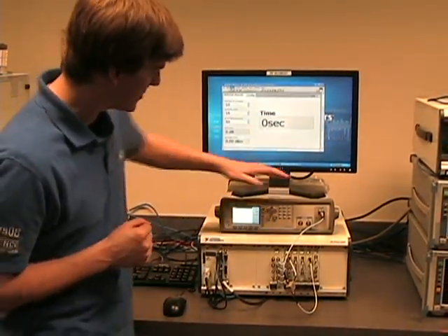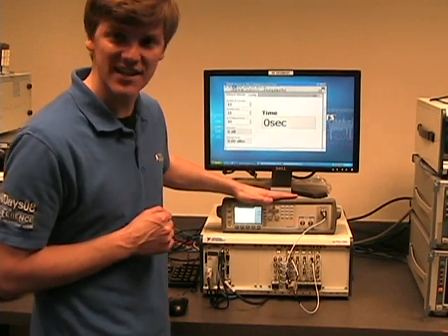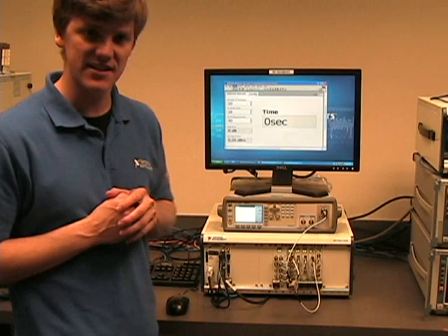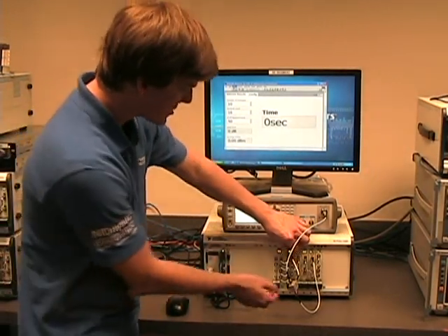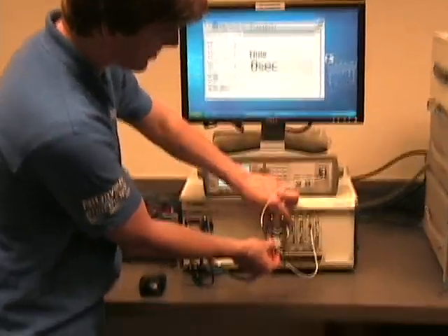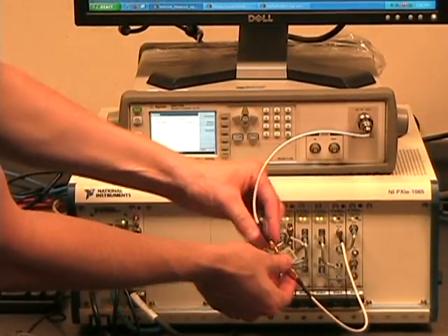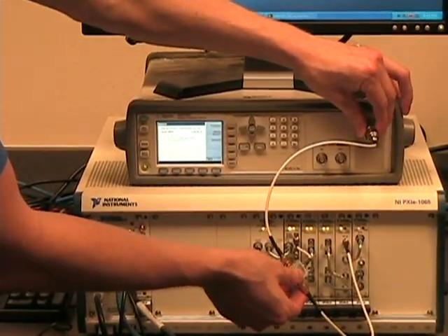And one of the things that we're going to find is that the high performance of dual-core controllers allows us to achieve significantly faster measurement times than with traditional instruments. Now the traditional instrument we're using today is the Agilent N4010A, which is one of the most common wireless LAN test systems on the market. So what we're doing is we actually are using our PXI vector signal generator, and we're splitting our signal out to a PXI vector signal analyzer, and then as well to the N4010A.